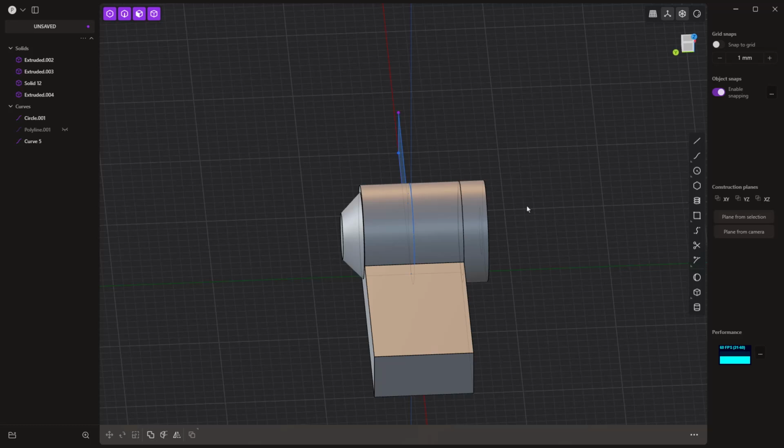When we're thinking about 3D printing, we have to consider tolerances, gaps, things that we need in order to make the parts actually work. If we're machining parts, we've got a much better control on tolerances, and we can deal with things like press fit or slip fit with very precise numbers. When we're 3D printing, we have to play it a little bit looser. When we're 3D printing these parts individually, we can make the tolerances a bit tighter because they can flex and bow, and it'll work that way. When we're printing them in place, however, the gaps in the tolerances need to be quite a bit bigger.